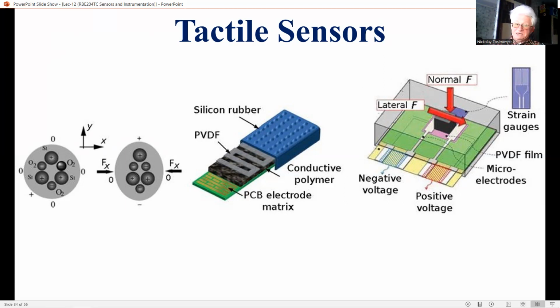One drawback of the material is the charge leakage. It means preventing the measurement of static images. Moreover, the material is also pyroelectric, which makes the sensor sensitive to temperature changes and gradients as well. And hence, this property could be put to use in robotics when thermal data about objects, like temperature and thermal conductivity, add useful information to the control system, somewhat similar to the human skin.